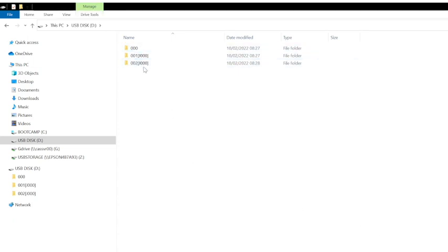So we've got our folder set up there now. What we need to do is add the sound files into the card. The sound files must be WAV or MP3. The WAV format maximum resolution is 44.1 kHz, 16-bit, and for the MP3 the maximum resolution is 320 kilobits per second. The tracks must have no ID tags, so no licensing in the actual files. If they do, the player probably won't read the file, or the file will be corrupted and won't play properly.